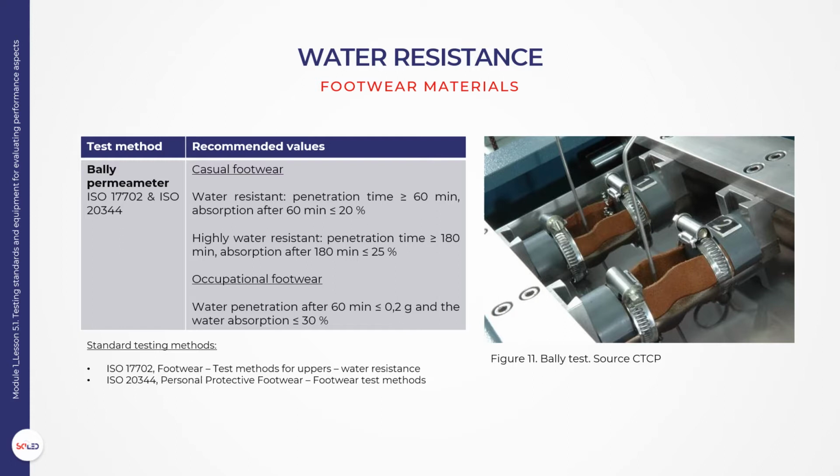Bally Penetrometer Test. Bally Penetrometer is applicable to all flexible leathers but is particularly suitable for leathers intended for footwear uppers. In these tests a piece is formed into the shape of a trough and flexed whilst partially immersed in water. The time taken for water to penetrate through the test piece is measured. The methods also allow the percentage mass of water absorbed and the mass of water transmitted through the test piece to be determined.